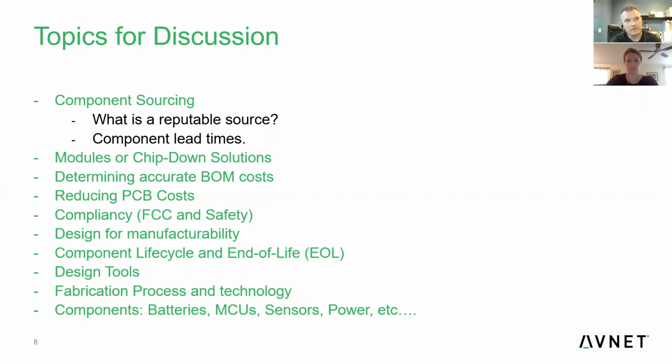FCC for a Bluetooth product versus a Wi-Fi product can vary, but just to put a price tag on what it would take, if you're starting out with a chip-down solution, you'd be looking at anywhere from $10,000 to $30,000. I know this is a broad range, and it depends on the complexity, but it tends to be in that range.